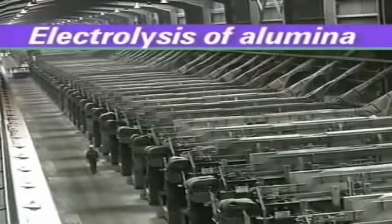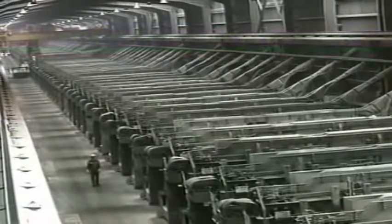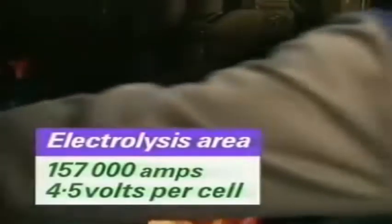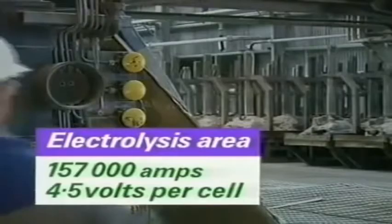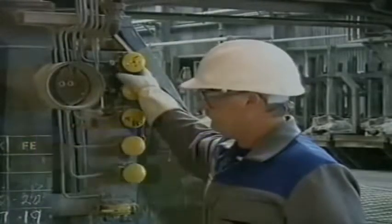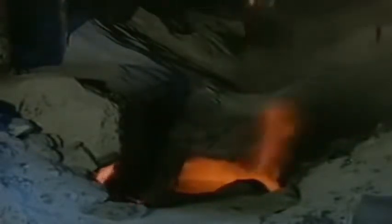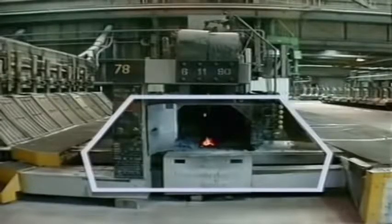This is one of the 4 rows of electrolysis cells called pot lines, where the electrolysis takes place. The current to the pot lines is about 157,000 amps at 4.5 volts. Anglesey Aluminium takes electricity from the national grid. This is one of the 312 cells in the pot lines. The electrolysis cell consists of a rectangular steel shell lined with heat-resistant brick and then carbon.